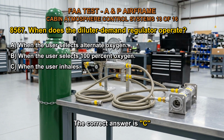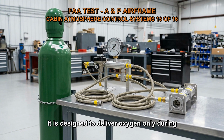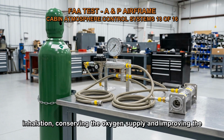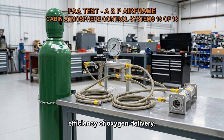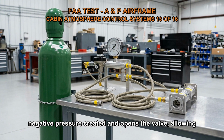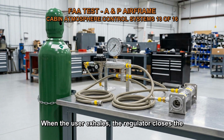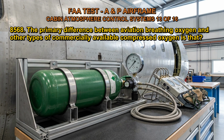The correct answer is C. The diluter-demand regulator operates when the user inhales. It is designed to deliver oxygen only during inhalation, conserving the oxygen supply and improving the efficiency of oxygen delivery. When the user inhales, the regulator senses the negative pressure created and opens the valve, allowing oxygen to flow into the mask. When the user exhales, the regulator closes the valve to prevent the loss of oxygen.